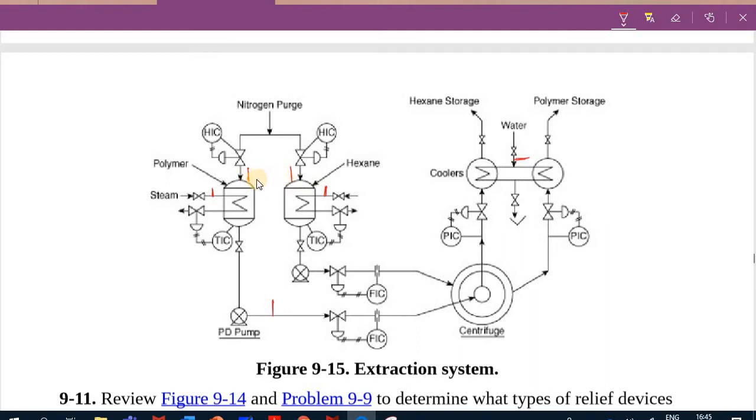And talking about the two vessels here, I'm going to use again a rupture disc and then a spring or a bellows one to also protect me from the backup pressure. And the rupture disc makes sure that anything in contact with this corrosive material would not affect my spring one. What about the ones on the steam lines? They're going to be safety valves, only gas, and the one on the liquid stream here is going to be a relief valve because it's for liquid. And here also for liquid service.